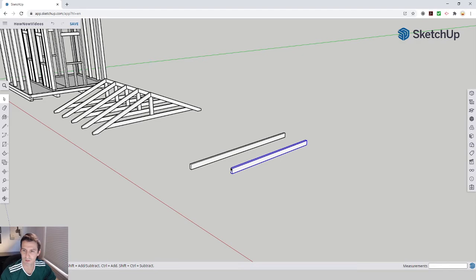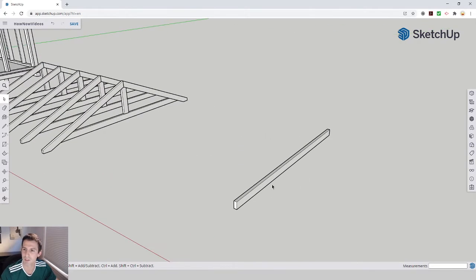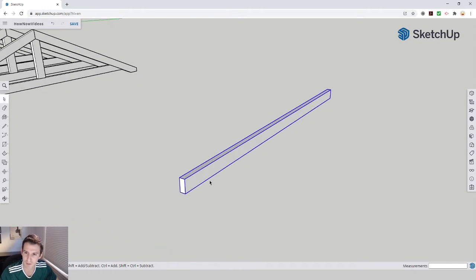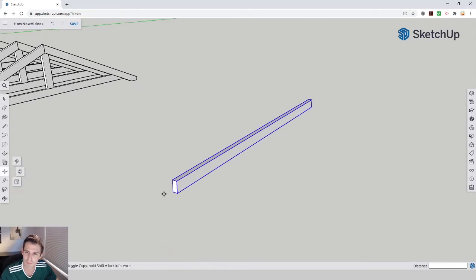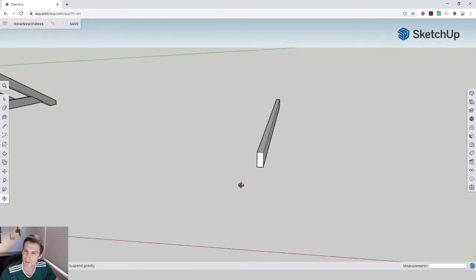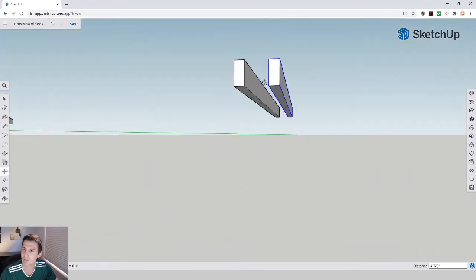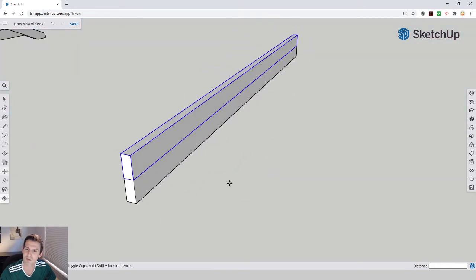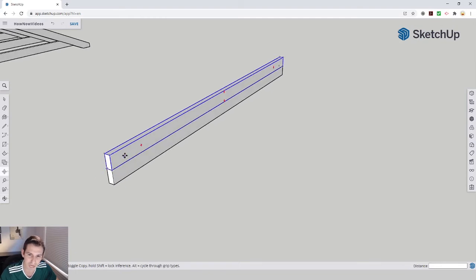So I'm going to take this original group object, and now I want to show you a command that has also been a lifesaver. Here I'm going to click on the move command. I like doing the move command and then tapping Control to make my copies. This way I can move my copy from the exact corner that I clicked on. So it makes stacking or aligning things into position a lot easier.